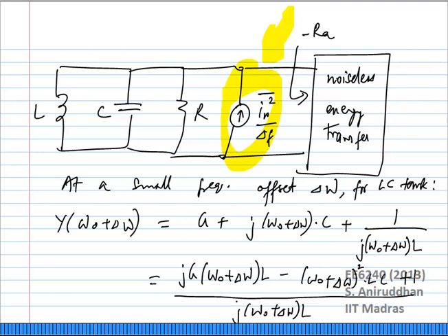However, suppose I took an ideal LC and put a resistor across it and then tried to analyze it, to build an oscillator. Mathematically this is very easy to try out in simulation. You take an ideal inductor, ideal capacitor, ideal resistor. Instead of building your RLC tank as L in series with R and some capacitance in series with R, if you build the tank like this in your simulator or in your analysis, you will still see a problem when you move away. So that is not the fundamental reason. That may be an additional reason why the frequency response differs from what we expect it to.